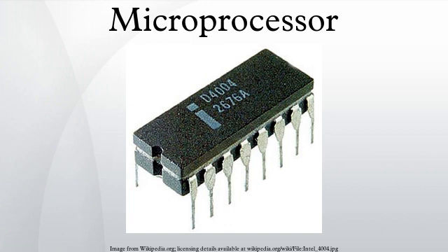The move to 64 bits by PowerPC processors had been intended since the processor's design in the early 90s and was not a major cause of incompatibility. Existing integer registers are extended as are all related data pathways, but, as was the case with IA32, both floating point and vector units had been operating at or above 64 bits for several years.